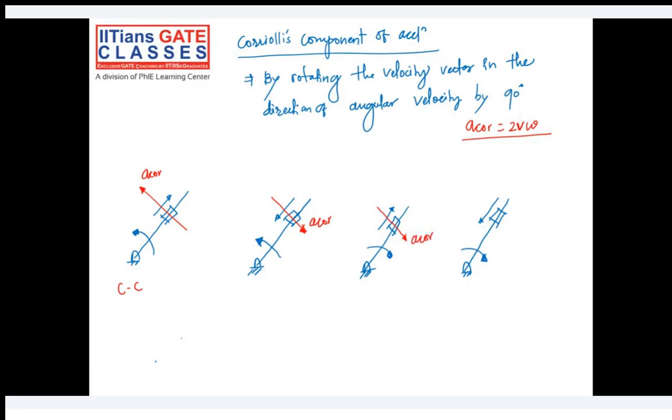Yes, sure. So whenever in a mechanism or setup we have the turn slide pair, in that case, the Coriolis component of acceleration will come. In other cases, it will not come, because the turn slide pair is generating this Coriolis component. It's a combined effect of the velocity of slide and the angular velocity of the turning pair. So that is the first point you should know.